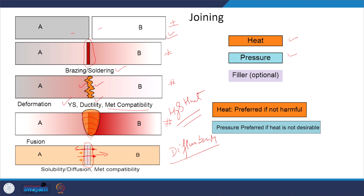In this case, there is no significant plastic deformation or bulk deformation, and there is no melting of the faying surfaces of the components being joined. Only diffusion across the interface takes place, and that helps in facilitating the development of the joint. It is always preferred that if the joint can be made without heat and without pressure, that will be the best.